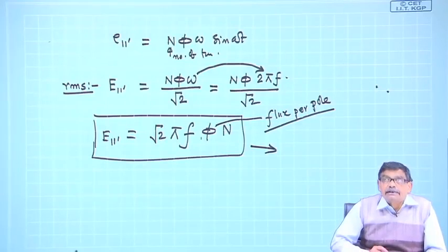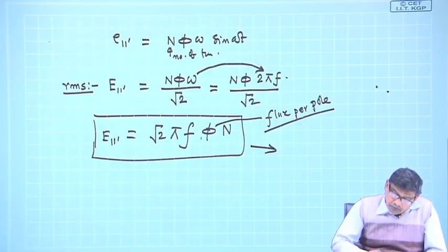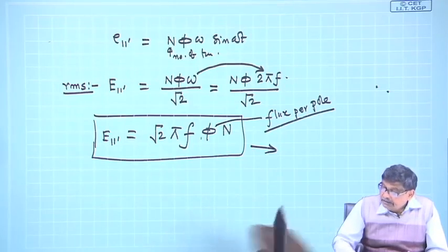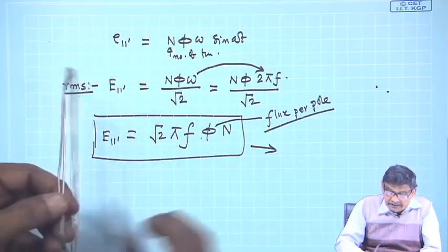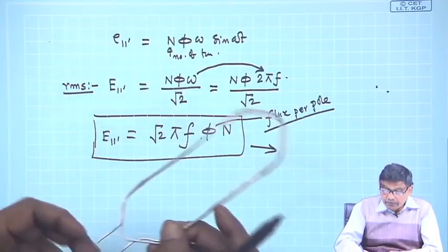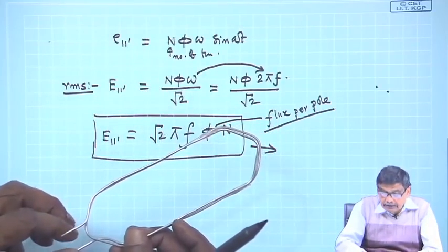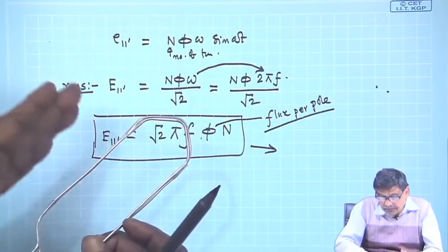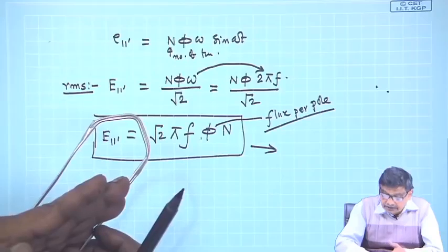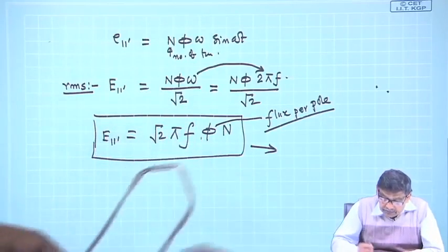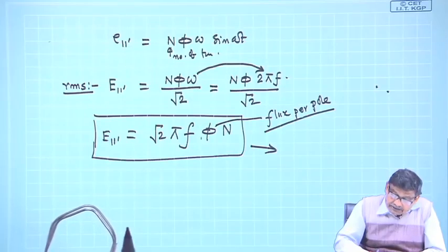You want to generate AC voltage. So, having n number of turns means this coil has n turns and they are placed in appropriate slots, so that you maximize the induced voltage. That means that if one coil side is under the center of the north pole, the other must be placed under the south pole, and they will be moving with constant velocity.